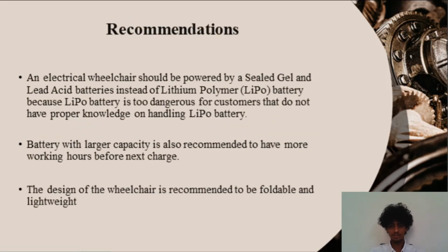Next, recommendation. To improve the functionality of Wheelie, the following recommendations can be made. First, an electrical wheelchair should be powered by gel cell and lead acid batteries instead of lithium polymer. Besides that, the recommended design of the wheelchair is to be foldable and lightweight, so the user is able to keep the wheelchair by himself. In future, Wheelie should be designed in a foldable, portable, and lightweight approach.